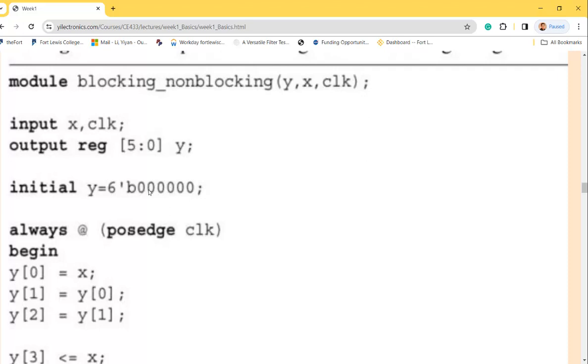It will be uploaded to the FPGA board that shows you the basis report. It's not a powerful computer here, right? With the compiler, you just program whatever, you can even plot, right? It's not. So now you are storing something to y. You are storing something to y as an initial value, and that's why you need to declare y as a register type, because it's a memory cell, or D flip-flop. It's storing something in there.